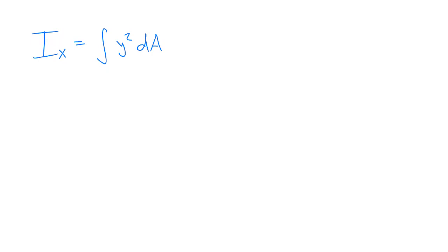So what I'm proposing is, this would be the basic formula for the moment of inertia with respect to the x-axis. What if I wanted to compute a moment of inertia with respect to some new axis? Maybe we'll call it x prime. And so I propose ultimately what we're doing here is we're taking the integral of not y squared, but y plus some distance. And I'm just going to call it d just to keep this simple.